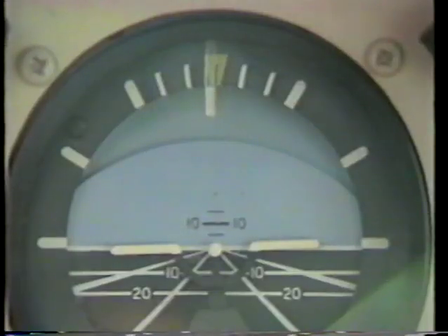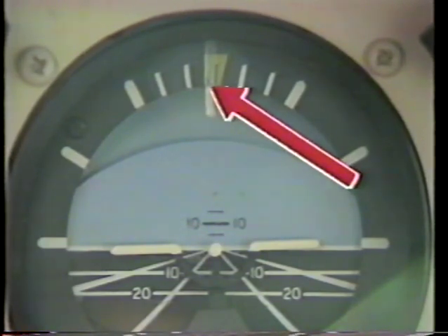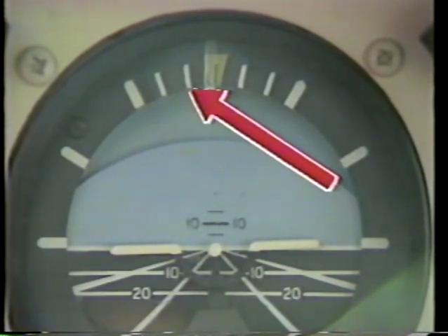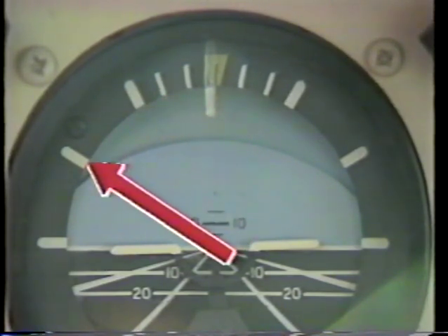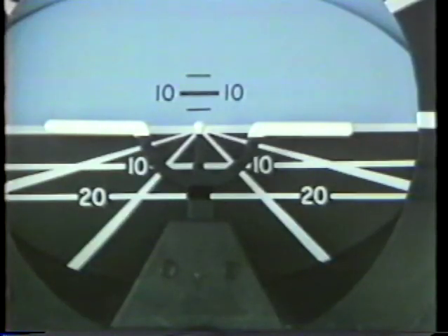Unlike the pitot-static system instruments, there is no delay or lag in the display of information. The attitude indicator provides instant indications of even small changes in pitch and bank. For exact bank information, there is a bank index on the face of the instrument with markings for the degree of bank: 0 degrees, 10 degrees, 20 degrees, 30 degrees, and 60 degrees. Angle of pitch can be read on the instrument face above and below the horizon line, from 15 degrees nose up to 20 degrees nose down.